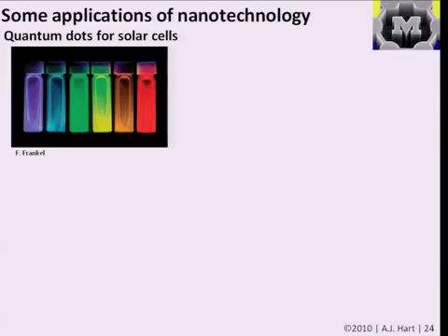Certainly, as things get bigger, you're going to have more flaws. The statistical distributions of defects and the effects of atomic defects on properties of nanotubes and nanowires are really not fully understood. Like, you can take an example. On the next slide, I'm going to show a picture of a TEM image of a quantum dot where it looks like the atoms are fairly well organized. You always, I guess, have some distribution of probability as something gets put together. But if one configuration is relatively more energetically favorable, then you're less likely, say, to form a defect.